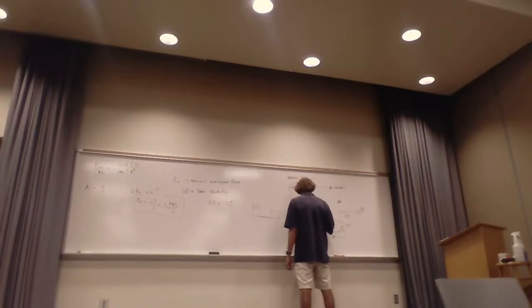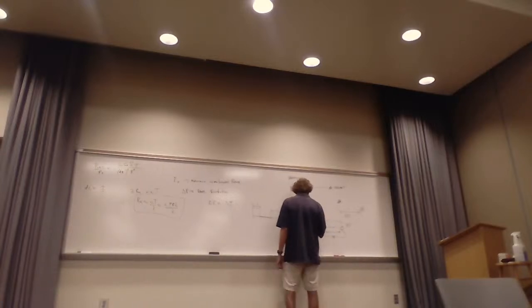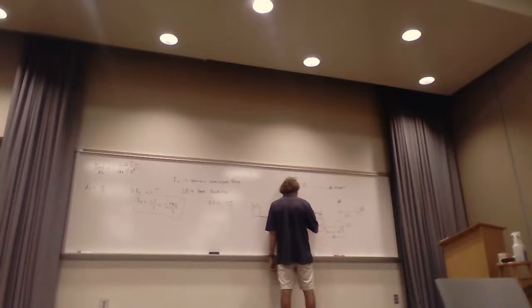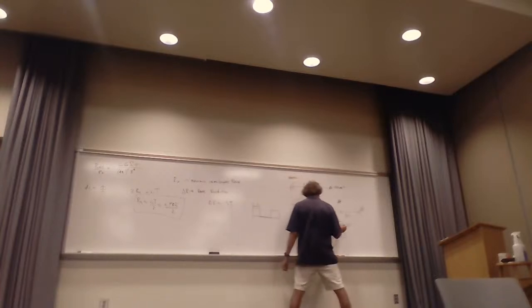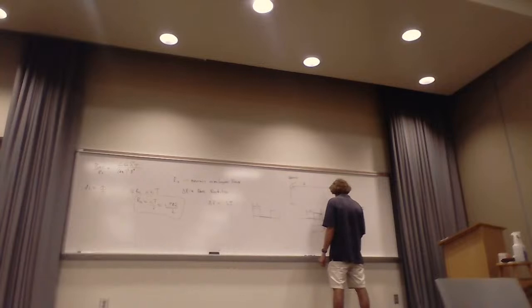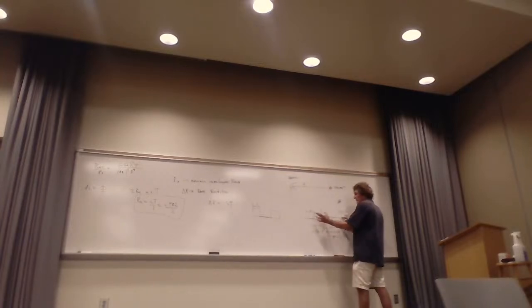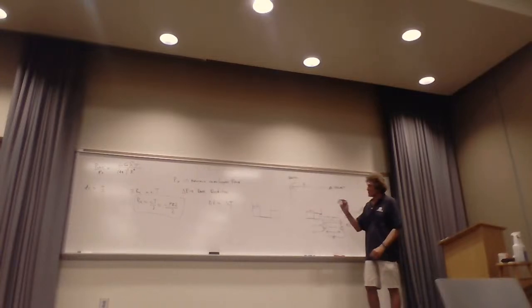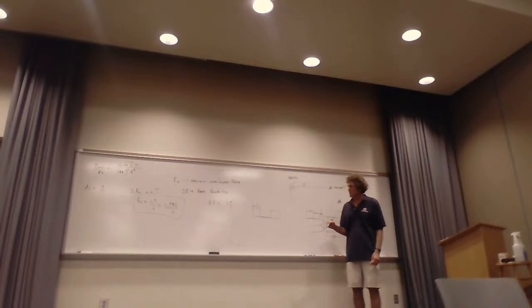Then as the signal keeps coming in, it gets longer and longer. This would be the reflected pulse coming this way, longer and longer. Now the pulse hits this, coming this way. You're going to find that the maximum possible distance you can get, so you have some dead spot between the reflected from here and here, back at that thing, will be C tau over 2.